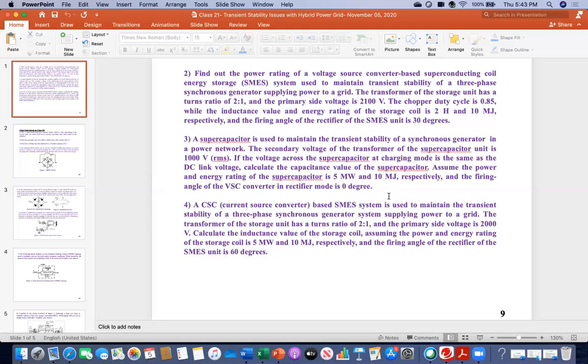Venkat, did you get the same thing? Yeah, I'm working on it, sir. Is your VDC value 1350.47? I need to check once. I got 10.96, Dr. Ali. I got 10.966. Oh, okay. Then fine. So Venkat, did you write the equation VDC equals 3 Vm over pi cosine of alpha?